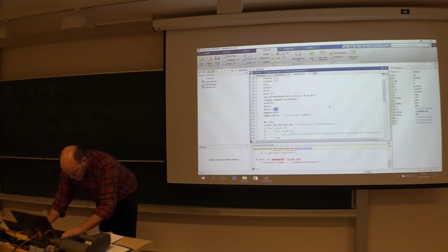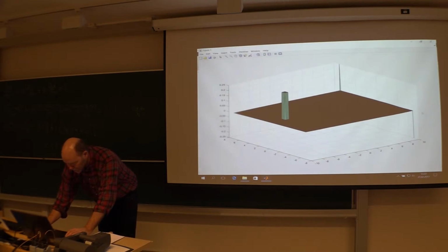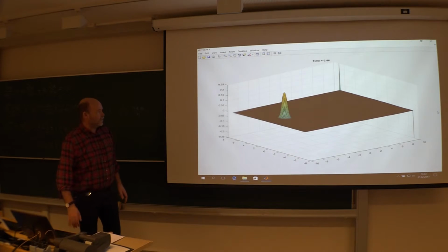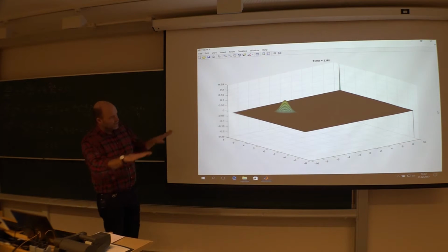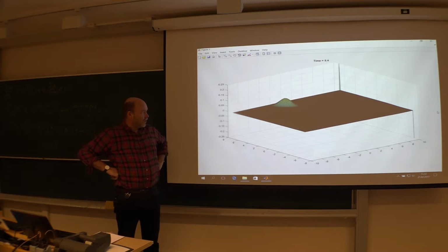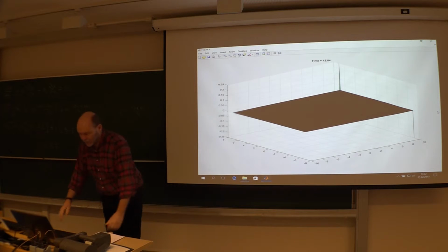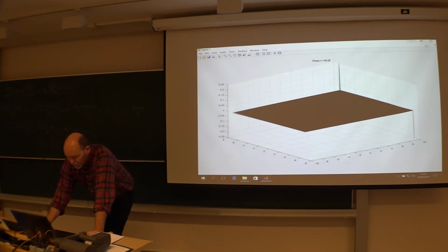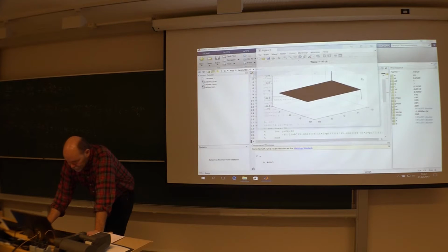So we need to keep it more smooth, you need a smaller one actually. To be on the stability limit here is not a good idea. So now you see it's quite smooth. Courant number is below 0.5 and it looks okay. But this smearing out effect, the diffusion effect, is still clearly present.